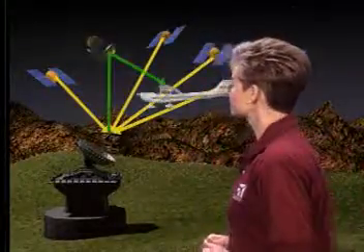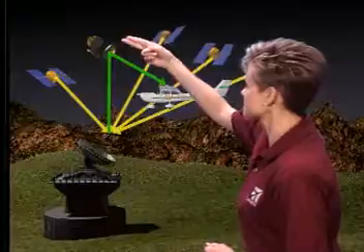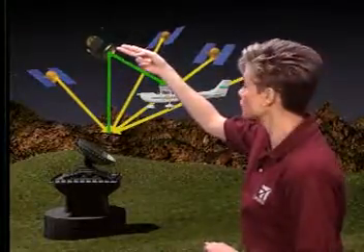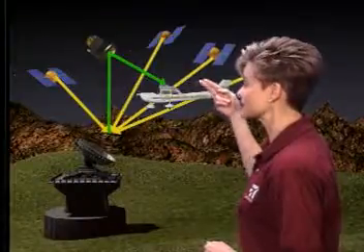This error information will be processed and sent to satellites in stationary Earth orbits. These satellites will then broadcast error-correcting information to the GPS receivers in aircraft. Now, that all sounds pretty complicated, but it should be unnoticeable to the users of GPS. What will be noticeable, however, is that this system will be accurate to nearly ILS tolerances on approaches.